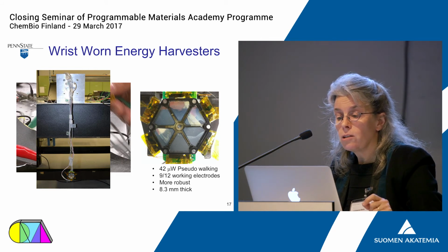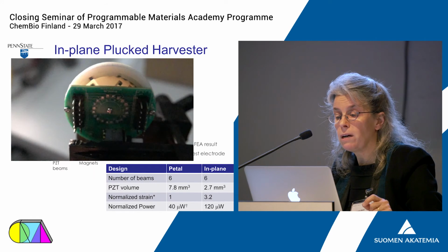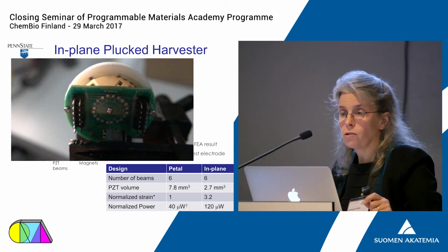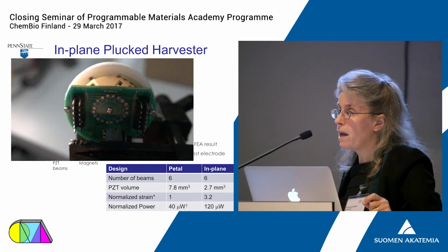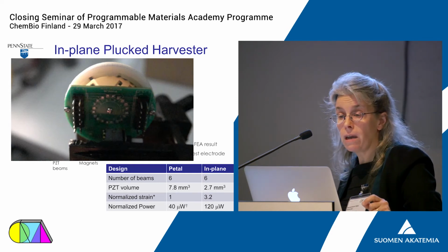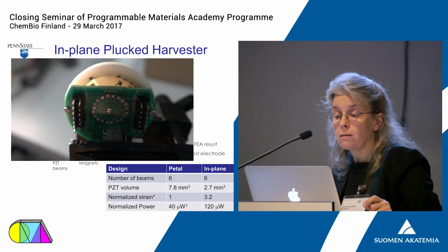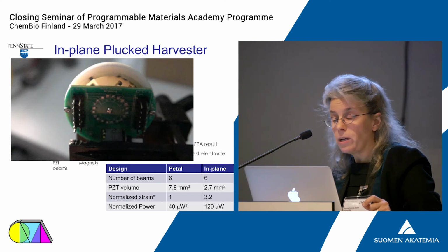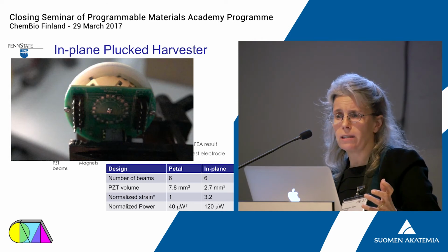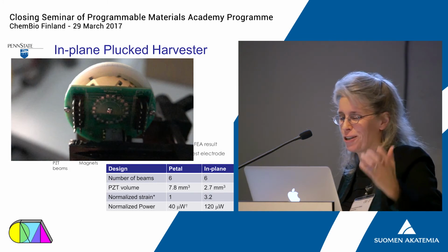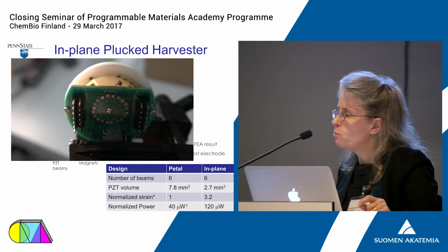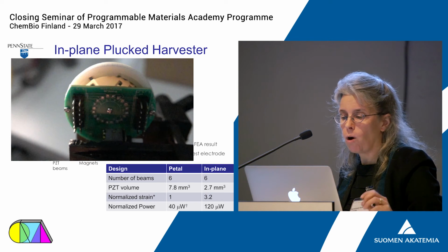And you can see that in this particular device, we have a series of petal-shaped piezoelectric cantilevers with magnets on the end. And we have an eccentric rotor that, as you move your wrist or swing your arm while you're walking, runs magnets in the eccentric rotor past the magnets on the piezoelectric, and it magnetically plucks the piezoelectric device. And you can see this is a swing arm. We built a mechanical arm since everybody is a little bit different in terms of the way that they walk, and we wanted to be able to estimate how much power we could get out for different people. We think we can get about 42 microwatts using a walking motion.